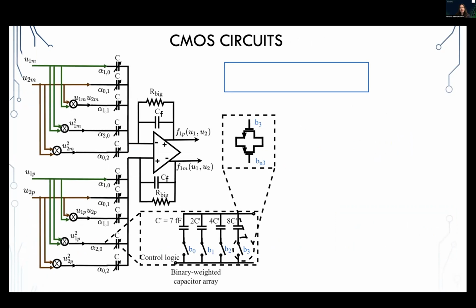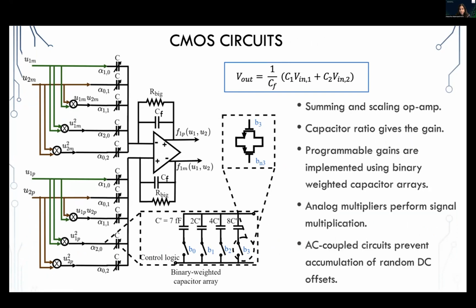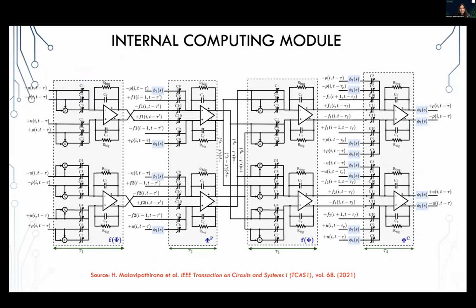This is the basic schematic block of the analog IC I mentioned. It is an op-amp based circuit. This is an op-amp based summing and scaling circuit actually. If you input several voltage signals, this circuit can scale and add those voltage signals. Here's another part of the schematic of the IC I showed. Actually, it is like 1/20th of the chip. We interconnect 15 of this kind of circuits to build the layout I showed earlier.